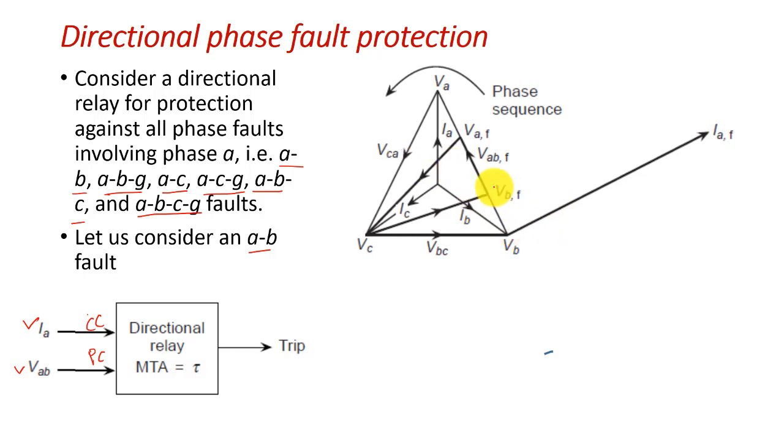You can see here in the phasor diagram, right? And also the magnitude of VAB will decrease, in the same direction as VAB. Okay, so it will decrease. The magnitude we can see here, now it became this much. So this is your VAB under fault condition. And current will increase. Already we have discussed this in the first or second class in the previous classes, right?